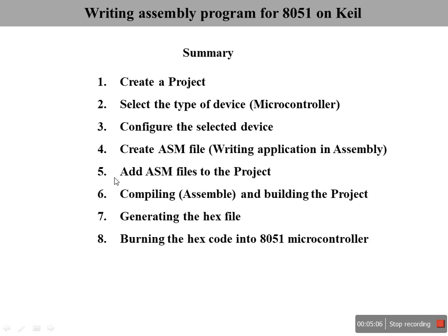After creating a file, add the ASM file to the project. In the first step you created a project, then you wrote assembly language code, then that assembly language file needs to be added to the project. After that, compile or assemble and build the project.